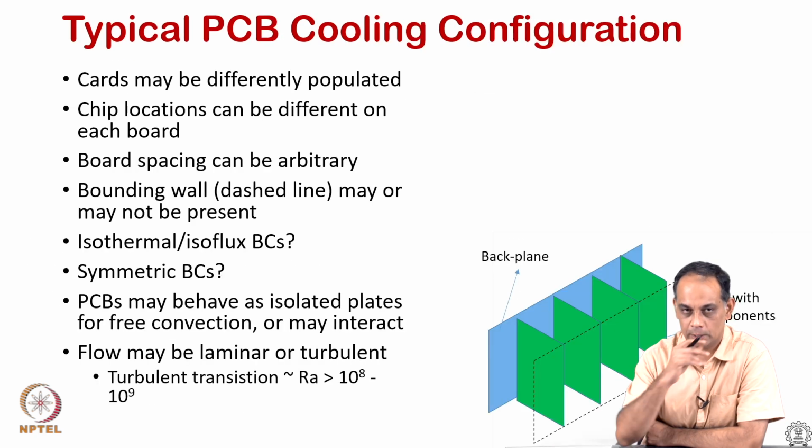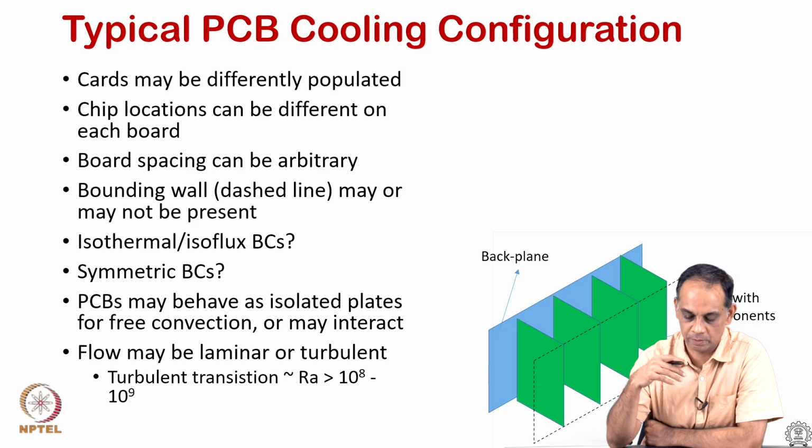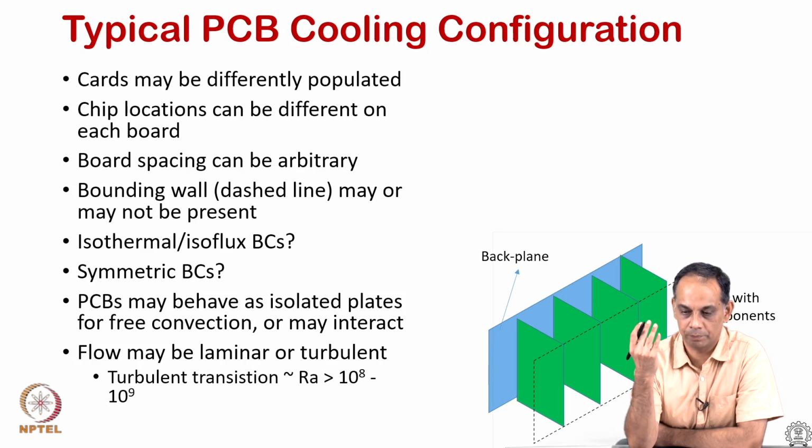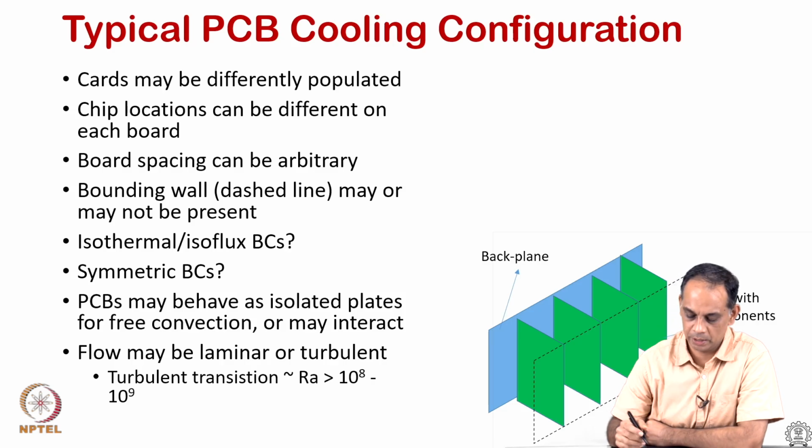Let us look at a typical PCB configuration. If there is a telecom type cabinet where we put a base station on a tower, fan failure is a very challenging situation. If a fan fails at the top of a tower, someone has to climb all the way to the top. So, typical telecom sectors may not prefer fans if they are not needed. Here is an example where natural convection cooling is employed, where there are